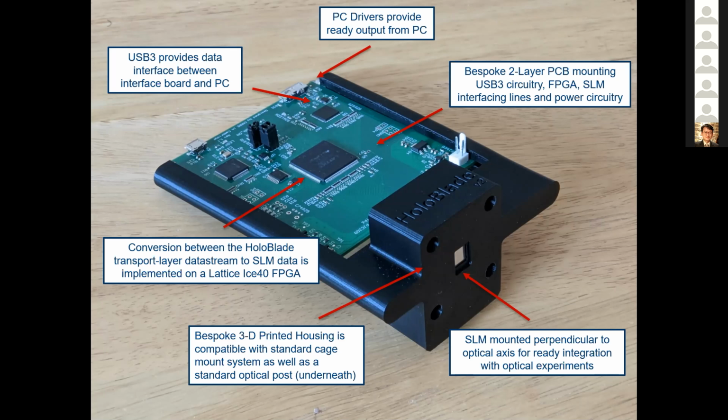The SLM itself is a press-fit interface into the front of the mechanical housing. So that just slots in there nice and tight and doesn't move anymore. And then there's a flexi ribbon cable between the SLM and the electronics board, as I talked about earlier. There were a lot of issues with mechanical strain damaging the flexi. It's quite a trivial thing, but a lot of time got spent on making sure that the flexi itself was appropriately strain relieved. So this current design handles that really well. This is not version 1. It took a couple of iterations to get it right.